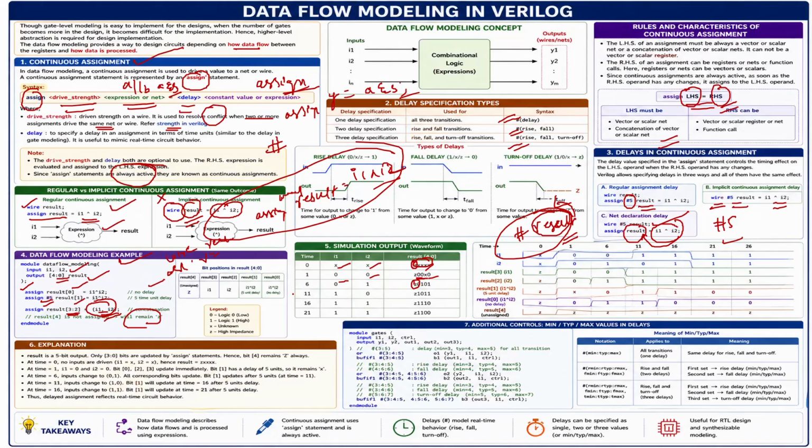Okay, the fifth delay you are giving, then at time unit 6 you are getting the value from the second output also. Result 1 also you are getting the output because the delay is crossed, right? 11, 16 and 21 also it is crossed. Then in all the cases result 4 should be a high impedance value only.